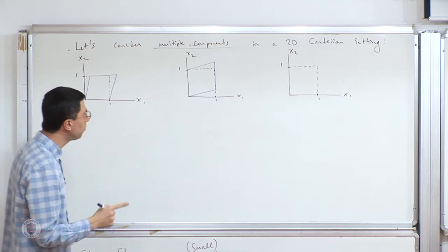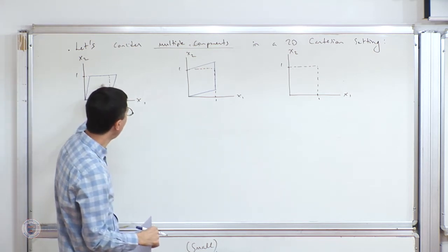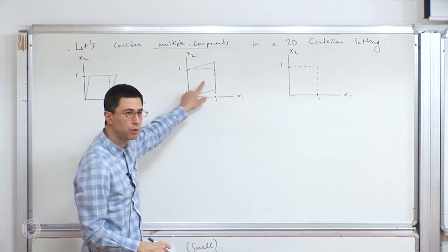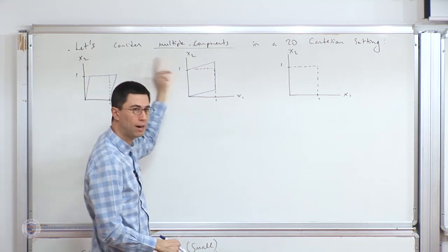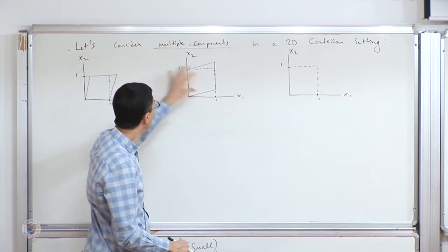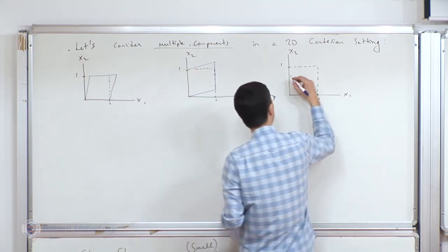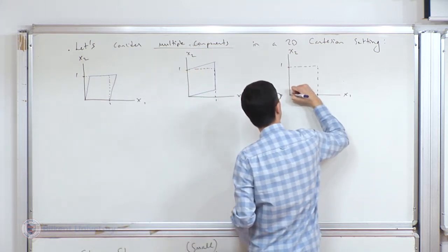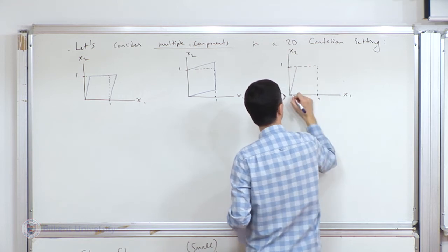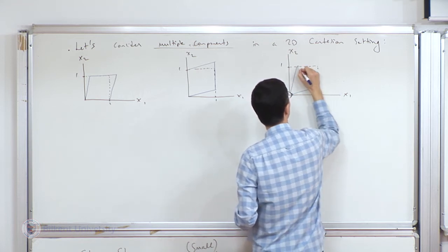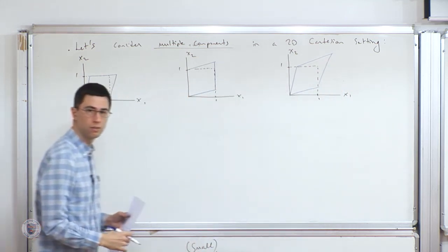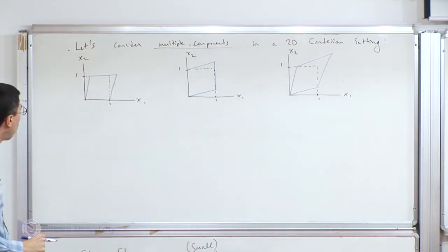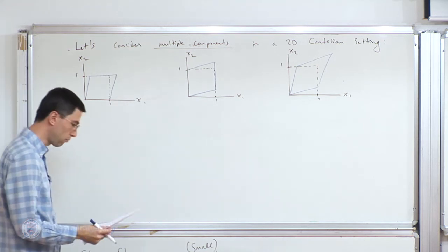I'm going to shear it both in the x1 and in the x2 direction. So it's a superposition of this onto that, or vice versa. So if you combine them, it's going to look like a trapezoid, but a rotated one. It's going to look like this. Okay. So blue is deformed, dotted black is undeformed.